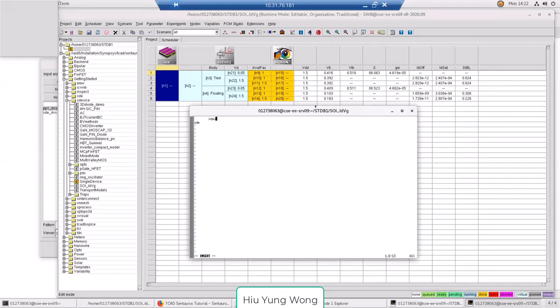It has an input file, and usually it has an output structure. So there's a convention in TCAD Sentaurus. The input file, we usually call it something underscore dvs.cmd. Okay, and then the output is actually ms.tdr. This is after mesh.